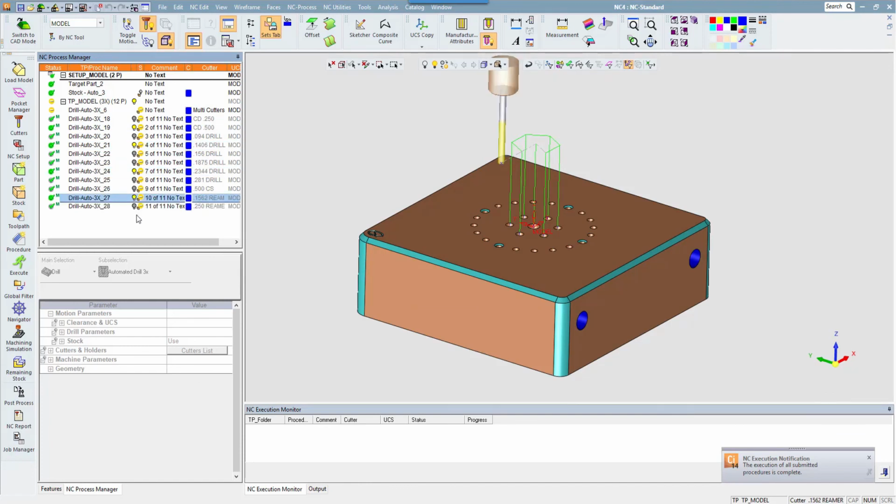So for folks doing water lines, pin drilling, really any of this stuff, the depths may be different each time, but really you're always going to cut 8mm taps to hold your block in, or you're going to do 16th pins, quarter pins. All this stuff is redundant, and that's what sequencing allows you to do, is fit to that geometry. Even though it's slightly different each time, your sequences will mold to it, adapt, and program the block for you. The goal is to reduce time with this, and it does a really good job of it when your sequences are set up correctly.